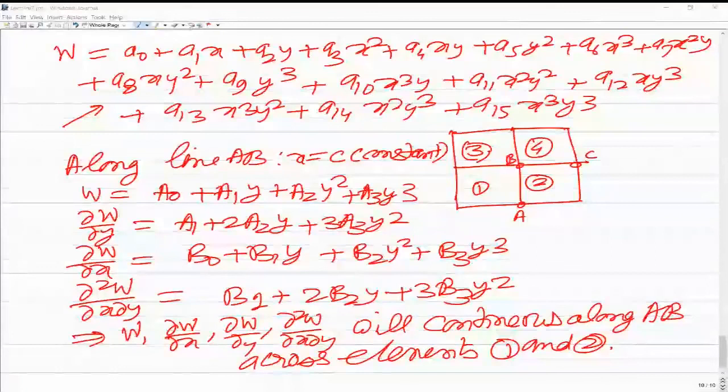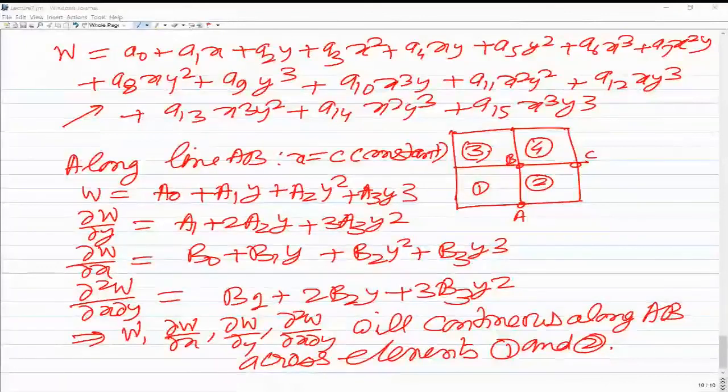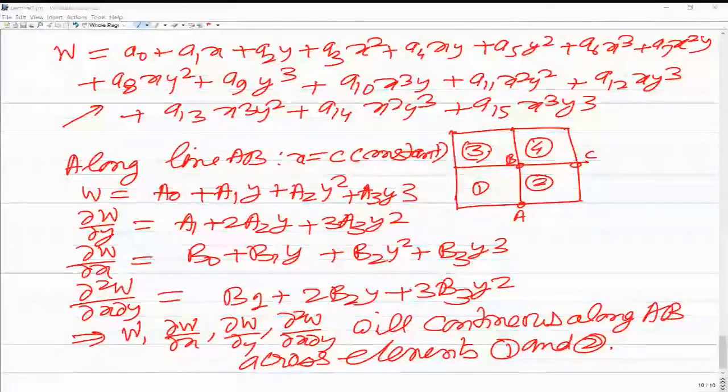Any other question? Sir, do we need to solve that assignment using the incompatible element? Yes, you have to use a 2 by 2 mesh, and you have to do it in MATLAB, because all the matrices, A inverse, the shape functions, and finding the integration of B transpose D B you can do using MATLAB.